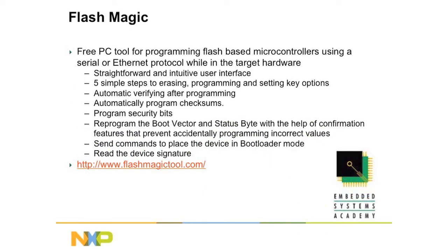FlashMagic is another tool that NXP is working on together with Embedded Systems Academy. This is basically a programming tool. You use it to program parts using either serial or an Ethernet protocol that we've come up with. The chips have a little bit of ROM that can communicate with the tool, which allows you to do in-field programming, or replace whatever firmware you have in a quick and easy way without having to break out your entire debugger and tool chain.